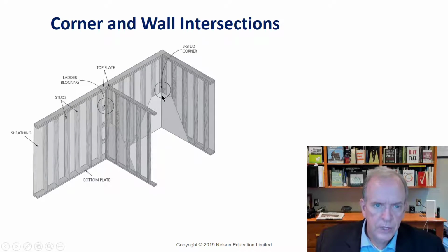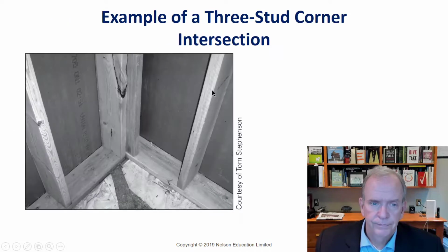The other consideration is if we have less lumber going through the wall, we have less thermal bridging, we have more room for insulation, and that makes a higher effective R value for the wall, because your studs and plates are not as energy efficient as insulation is.